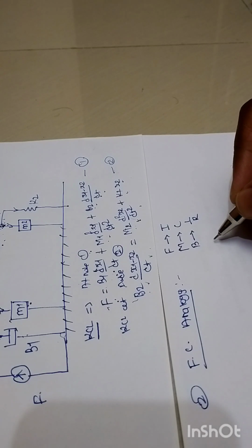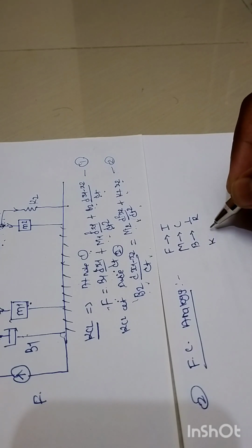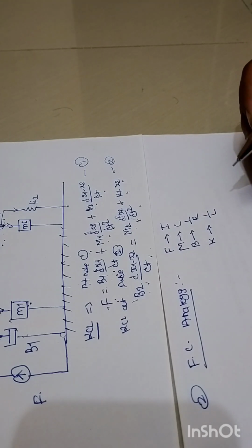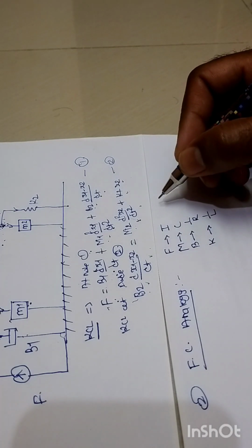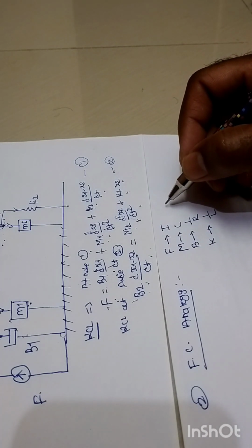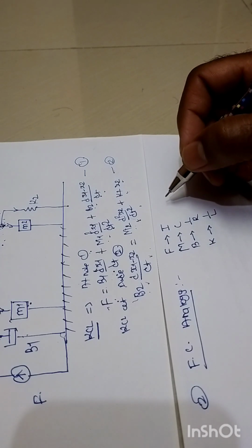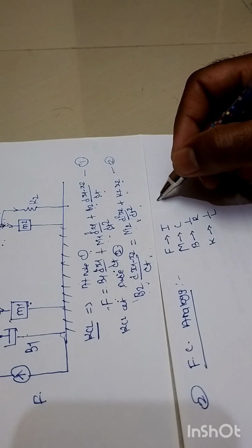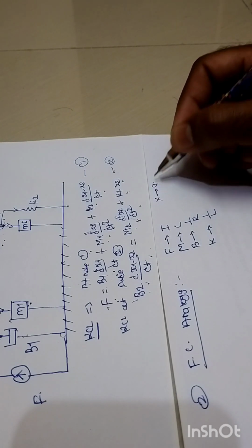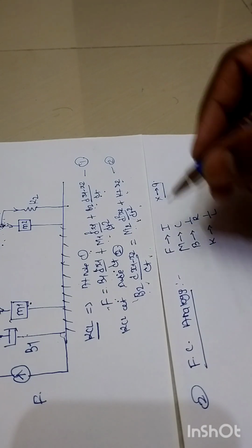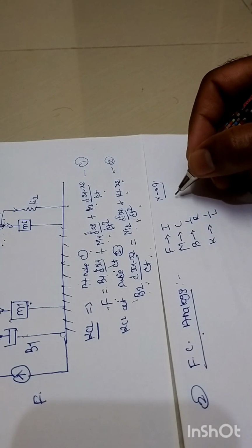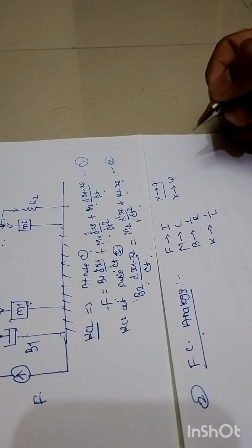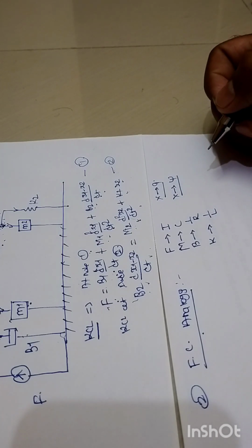And the third important element is the spring, K. So this K is analogous to 1 over L, that is inductance, right? And the way in which we had replaced displacement in force voltage analogy, where X is analogous to Q, similarly in force current analogy, this X is replaced by the flux linkage, that is psi, right? So these are the analogous terms that we need to remember.